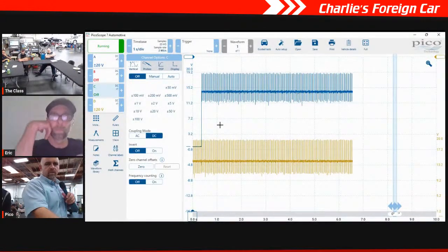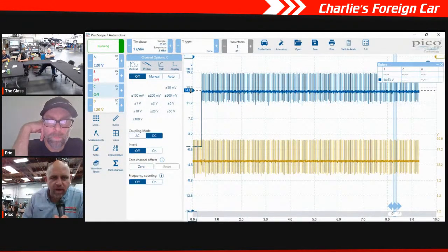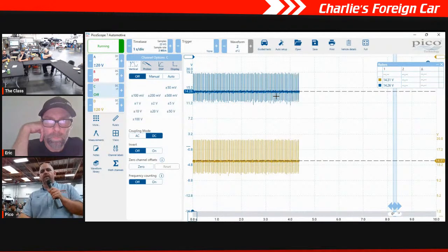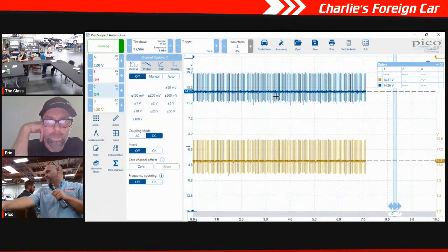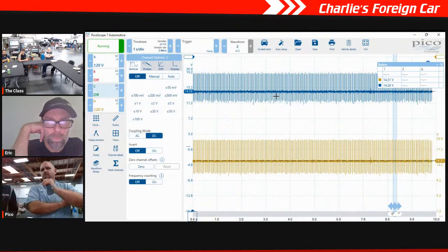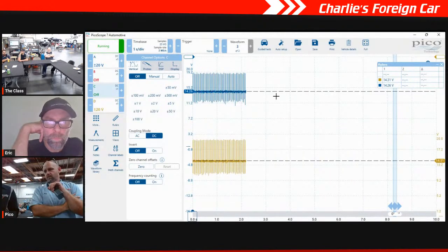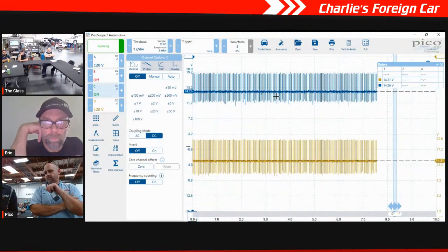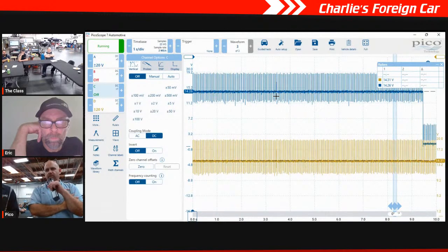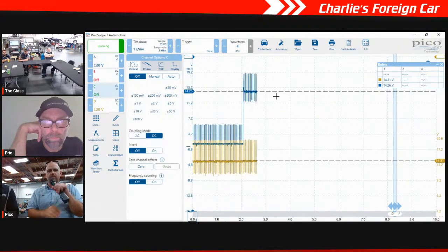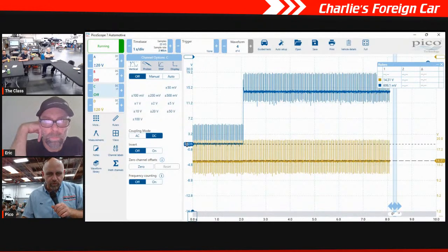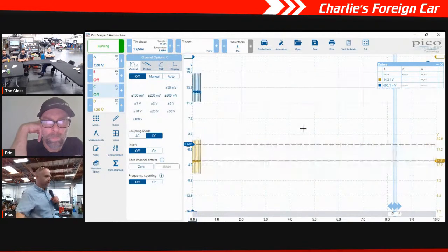Okay, close that. So now we're on the exhaust. We've got 14 volts there. We've got 14 volts there. So now go ahead and activate with this. We need to know which one grounds. The blue is going to ground. All right. Okay, so we activate it. Yes, Gianni is correct. The blue one grounded. And the blue one went down to 0.6 volts.